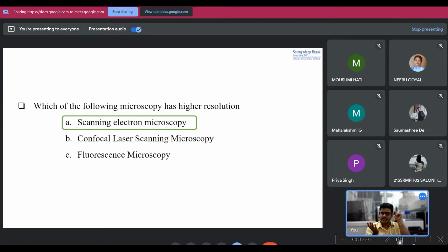Because the electron beam is there, and the secondary electrons getting out from the gold coating or the metallic coating on the sample are the only ones being detected by the secondary electron detectors. The electron beam is not getting inside the sample itself. While in TEM, the electron beam is transmitted, going inside, and whatever electrons are left are detected by the detector below the sample, right?